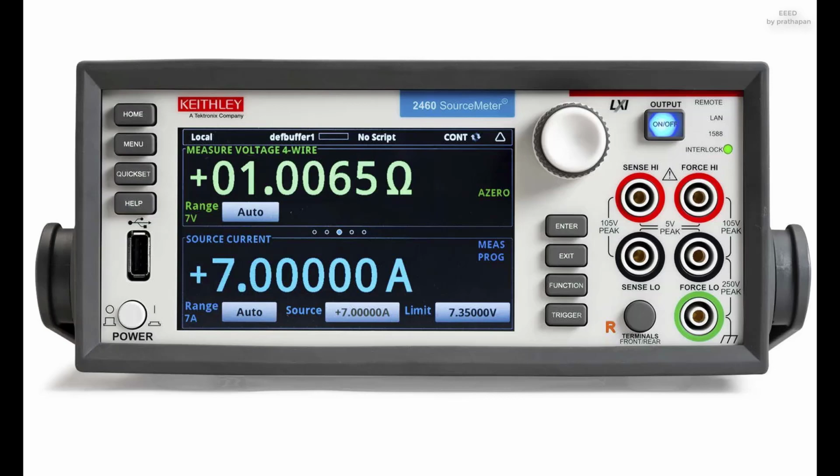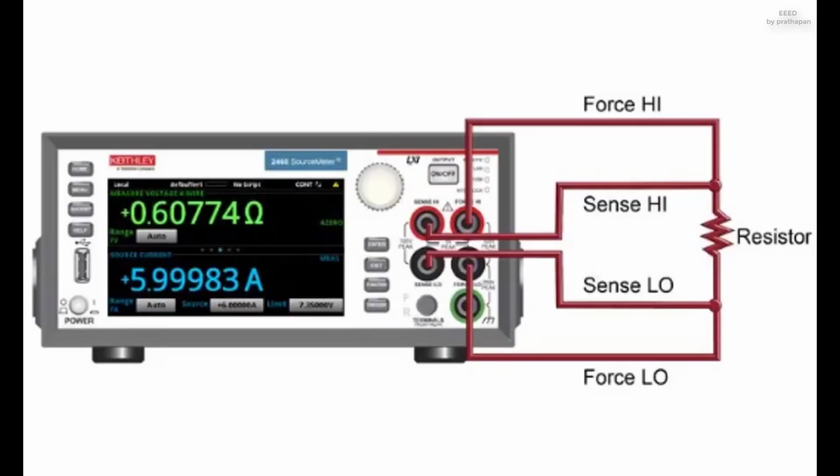A simple ohm meter may apply a voltage from a battery across the unknown resistor, with an internal resistor of a known value in series, producing a current which drives a meter movement. The current, in accordance with Ohm's law, is inversely proportional to the sum of the internal resistance and the resistor being tested, resulting in an analog meter scale which is very nonlinear, calibrated from infinity to 0 ohms.